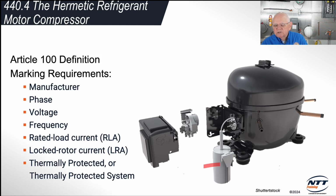We need some way to terminate our incoming power, don't we, to that compressor on the inside, to that motor. And so we have some means to do that. What's critical for us is to properly size those conductors and protect them properly. What's required to be on the nameplate? What's called the marking requirements. And that's found in Article 440, in 440.4, I believe it is. Yeah, it says that right at the top of the screen, 440.4.